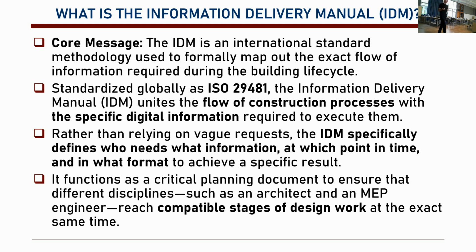ISO 29481 is the standard code for that. IDM unites the flow of construction process with the specific digital information required to execute. So, for instance, it tells what information is needed by whom, at what point, and in what format.